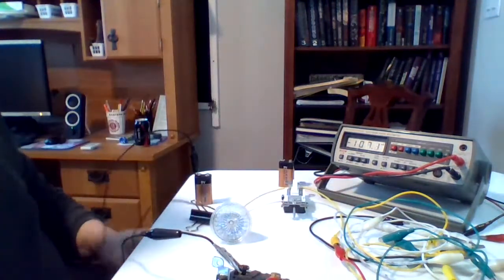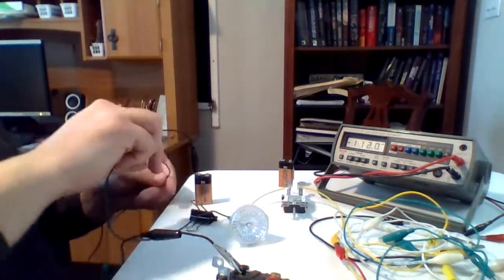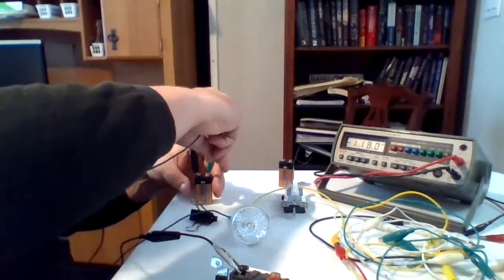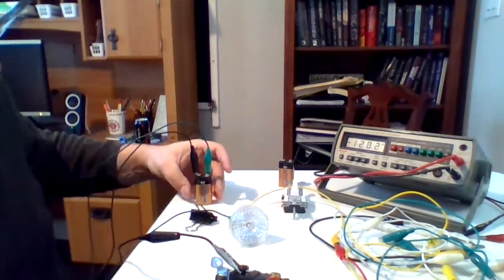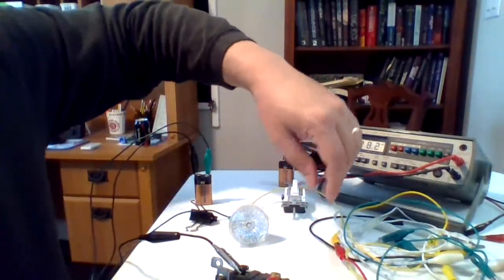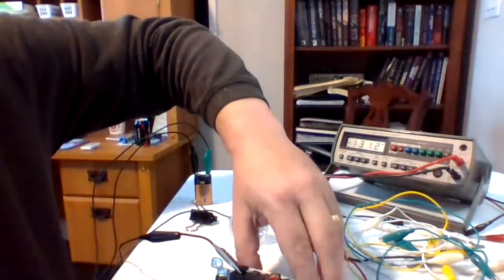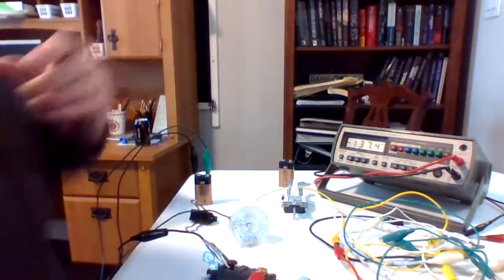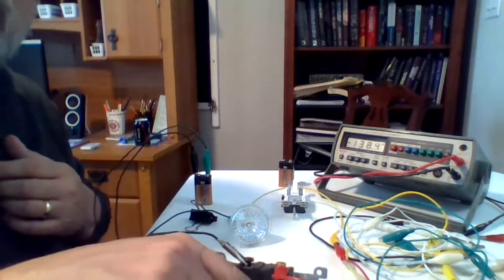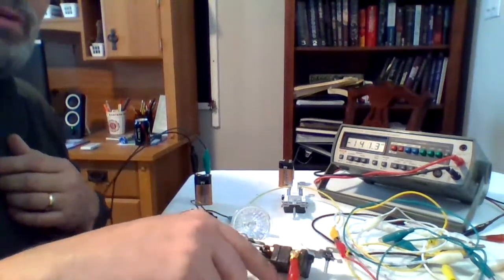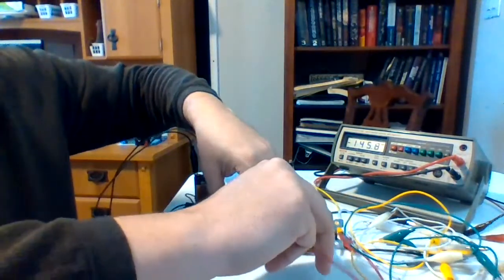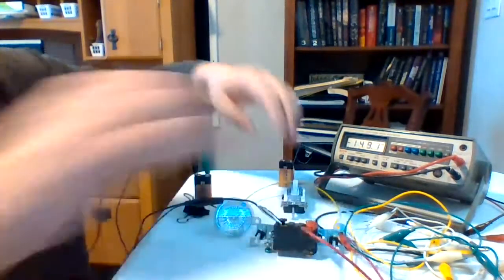And then this part here, I can hook into. What will happen is that if I flip the switch, the light turns on. If I flip the switch, the light turns off. So I'm actually treating this switch, even though it's a double pole, since I'm not using the other pole, like a single pole, single throw switch.